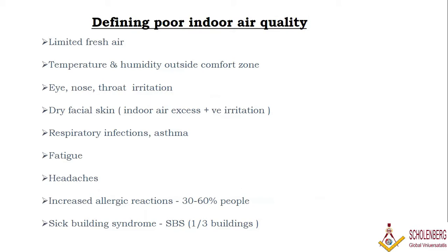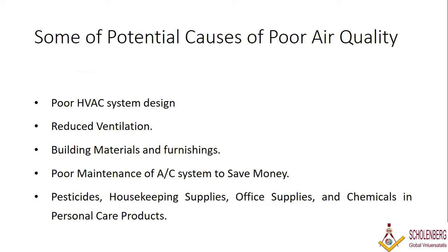Now, generally, how do you know as an HVAC engineer that the indoor air quality is very, very poor? Many times you go to the hospital, you can find sometimes throat irritation, dry facial skin, respiratory infection, asthma, fatigue. Sometimes if you stay a long time, you will have a headache. Then you may have allergic reactions in certain areas. Then we also have sick building syndrome. These are some of the indicators of poor indoor air quality.